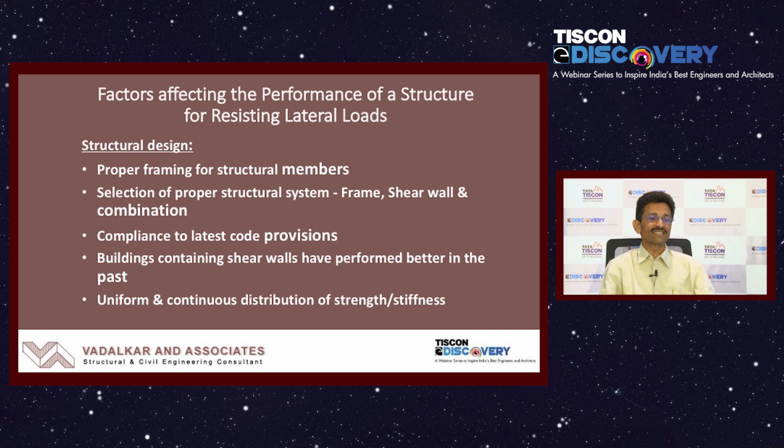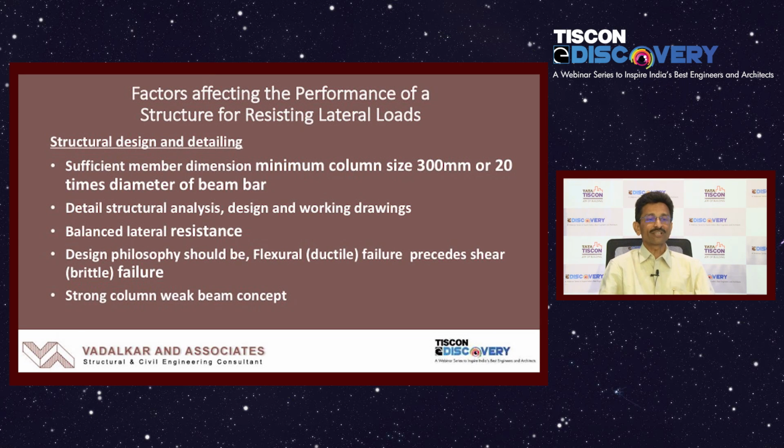Now as far as structural analysis and design are concerned, of course you need to have a proper structural framing system and members. You have to comply with all the latest code provisions, and proper frame and shear wall structure interaction can of course be used in the planning. It has been found that buildings containing shear walls have performed better in past earthquakes. So that is a suggestion by the code also, that if you have a shear wall system, it is much better. And of course, if you can keep uniform and continuous distribution of strength and stiffness in the building, that is of course desirable.